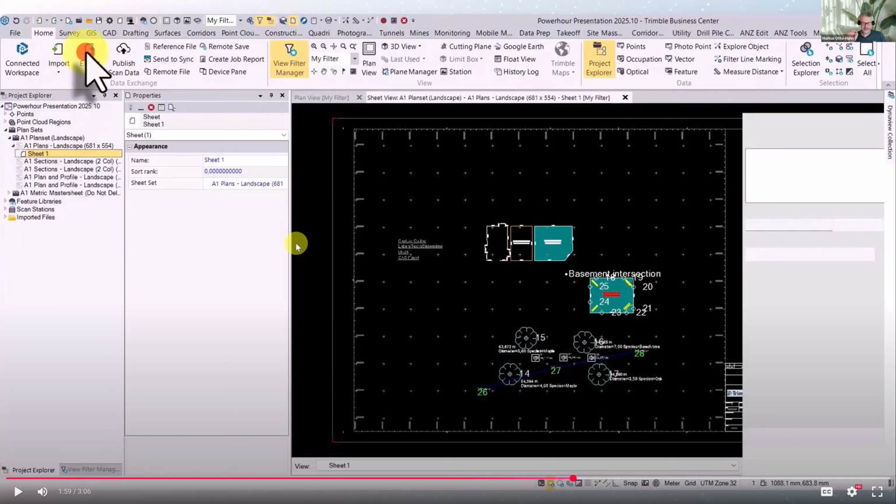If I only select the sheet, I just select the layout or the sheet view for export. This means I select the frame, the grid, the title, and a window, a DynaView, where I can see my model data. But the model data itself is not selected in that way.